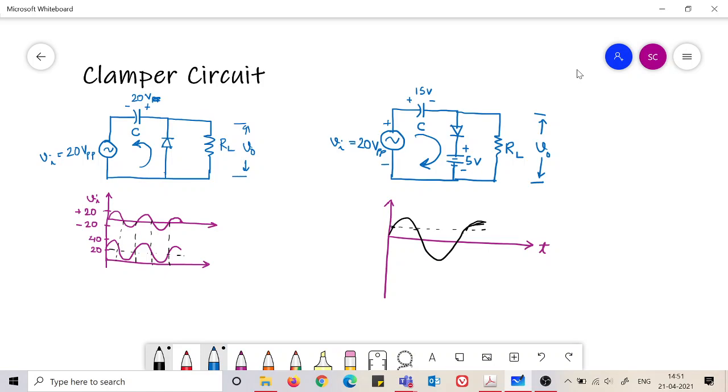So you have to increase this voltage, and when Vi is 10 volt, then 10 minus 15 is minus 5, and the voltage across this would be minus 10. Still it is reverse bias, so we need to have this voltage more than 5. Only when Vi is 20 volt, then it is 20 minus 15 and you get a plus 5 here.